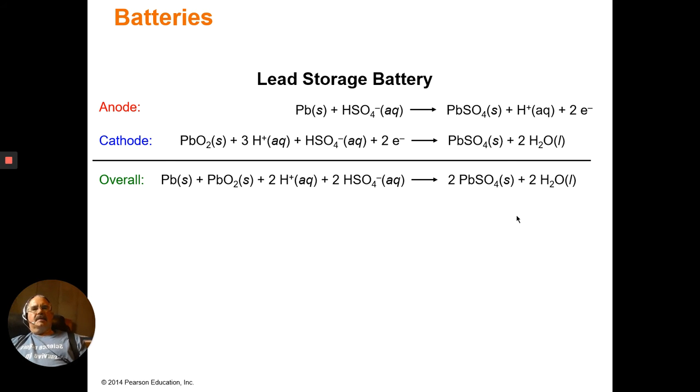One of the ways that they test car batteries is to use this pipette that contains floating balls, and if the battery is good, you still have a lot of sulfuric acid, which is considerably denser than water, and so all the balls would float. But if the battery is run down, then you'll have a lot of water, and some of the balls would sink.